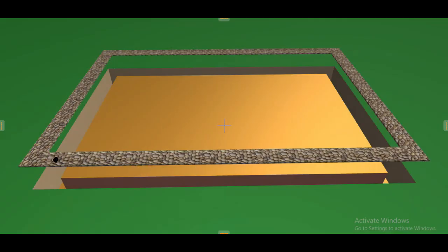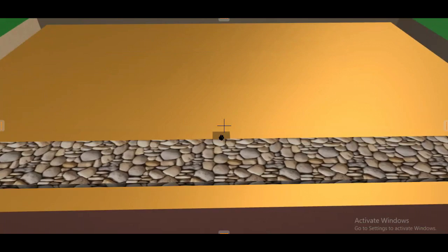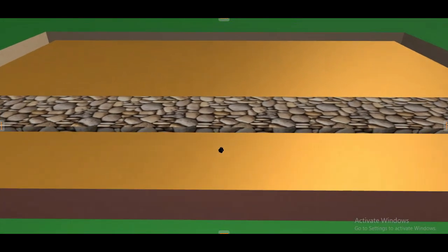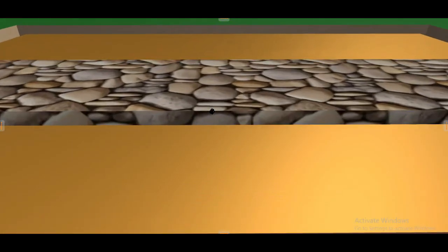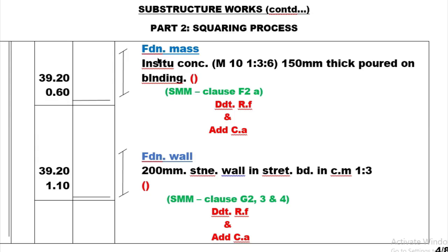And the girth, I'm taking it from the center line and it is 13.20 by a width of 0.6 meters from this edge to this edge. So it is what I write in the dimension column and then I square. But if I want to get a volume, I go further and multiply by this thickness, from this upper edge to this lower edge, that is 50 millimeters, to get the volume, which I now carry forward to the bills of quantities.